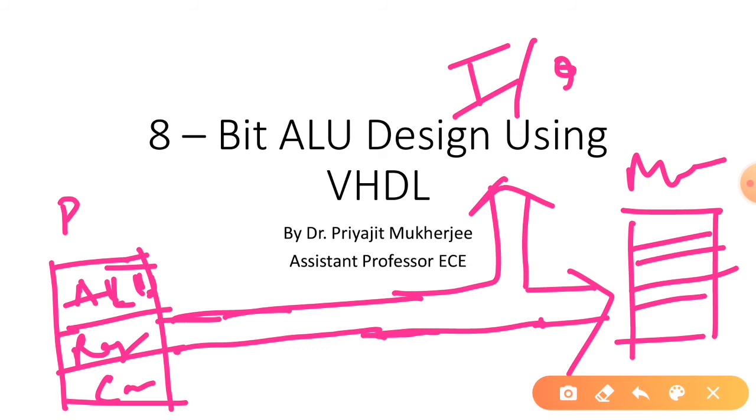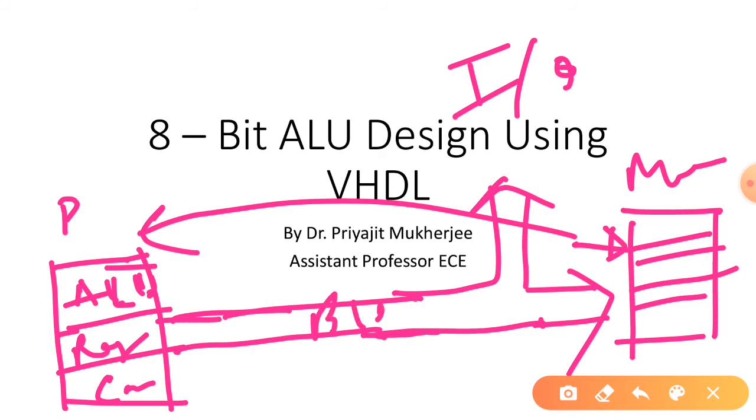Then we send the initial or starting address of the instructions to the processor, and once we send this, the processor will start execution of those instructions one by one with the help of this bus. In this case it will be using the address bus and data bus. In the address bus it will send the corresponding address of the memory block. Using the data bus it will fetch the data.